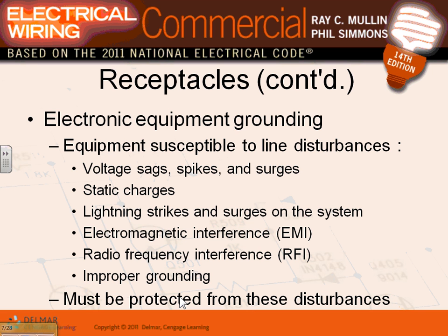Electronic equipment, guys, there's a bunch of things. For sensitive electronic equipment, we also use surge protective devices. I don't know if you remember what Todd was saying. So, number one, guys, you use an isolated ground receptacle. That's just to minimize interference from signals on a conductor or the conduit being used as an antenna, grabbing all this noise, also called stray signals, and dumping it across your cashier device or your computer. So to minimize this, we use an isolated ground receptacle.